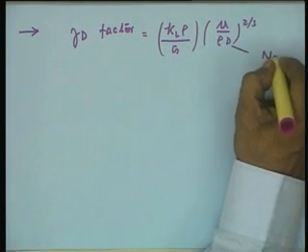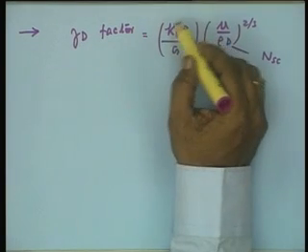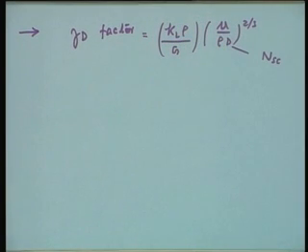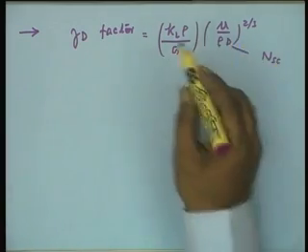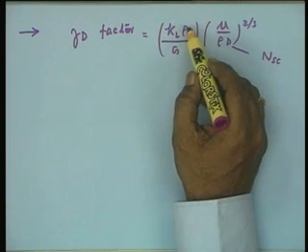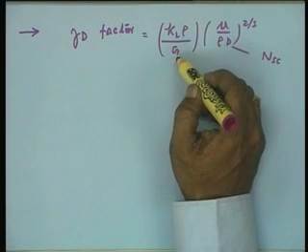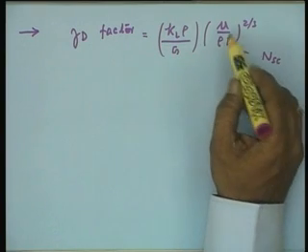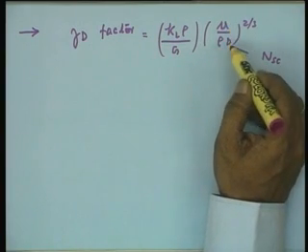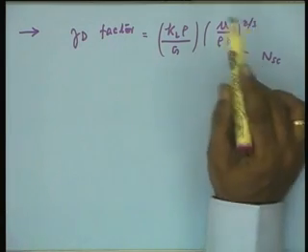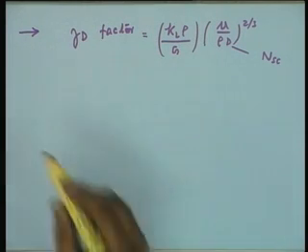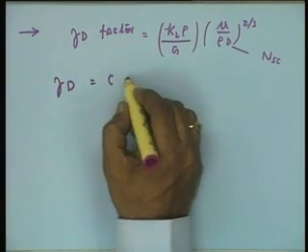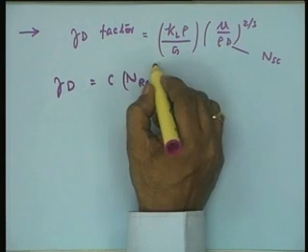Now, this essentially is the Schmidt number. So, basically the first term in the parenthesis represents the mass transfer function, the other is a dimensionless number which gives you the operational parameters, and here KL is the mass transfer coefficient, rho is the density, G is the superficial mass velocity, and mu is the viscosity, rho is again density, and D is the diffusivity. And this lumped parameter has been shown at least empirically in a large number of experimental data. It has been noted that your JD is equal to C Reynolds number to the power minus n.